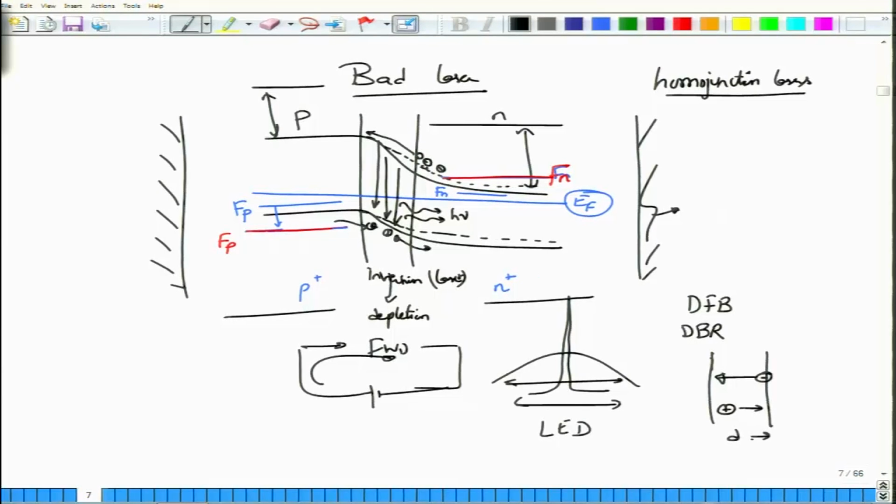The length of this region, unfortunately, is very small, because it is governed by the diffusion and the lifetime of diffusion. So, this is the diffusion constant and this is the lifetime constant, which is usually measured experimentally, and the diffusion constant is determined by rather complicated calculations which we do not want to go into. But the idea is that the length over which the inversion layer exists is actually uncontrollable, because these quantities are usually not in our control, they are material properties and they are also temperature dependent. So, it is uncontrollable and it is actually very thin.